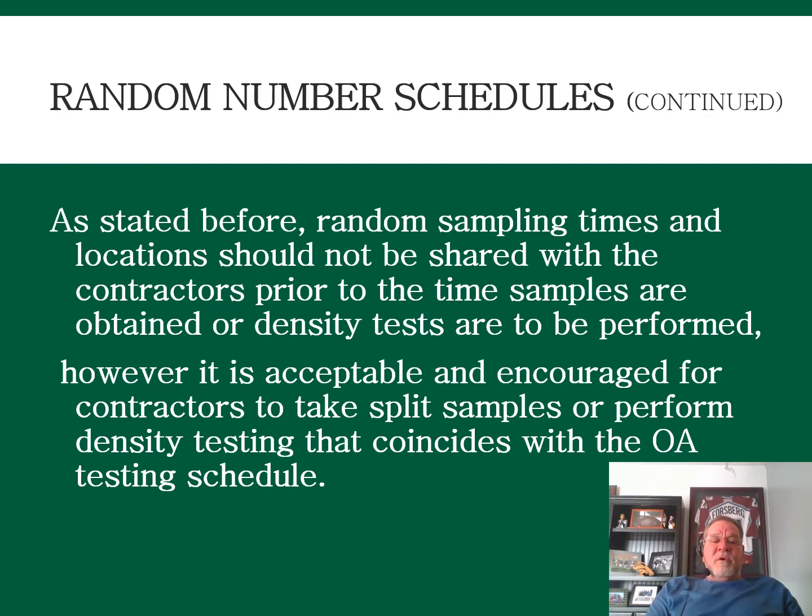As stated before, random sampling times and locations should not be shared with the contractor. It's acceptable and encouraged for the contractor to take a split sample or to perform density testing that coincides with the QA or OA testing schedules. Most contractors, when a random is being taken, will also take a split sample from that position.